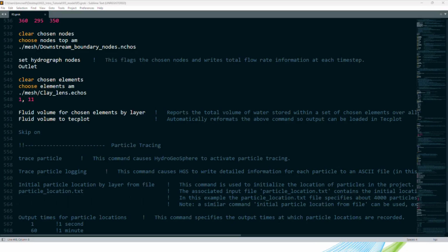So, okay, can I provide a little bit more detail on the reactive transport capabilities? Can HGS simulate multi-phase flow, phase partitioning? So the reactive transport capabilities of HGS are relatively simple. We support first and zeroth order reactions. We support chain reactions, although not branching chain reactions. You can have multiple solutes that are transported as advection, dispersion, diffusion reactions. Multiple solutes can be tracked in parallel, but you can't really have complex multi-component reactions, if that makes sense. In terms of multi-phase flow, really no capabilities there.